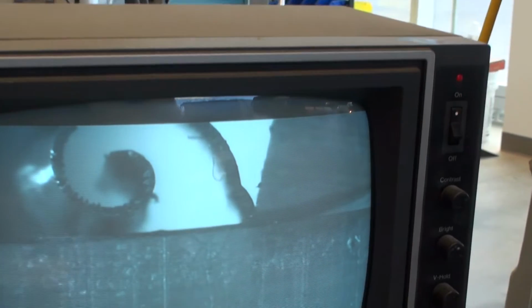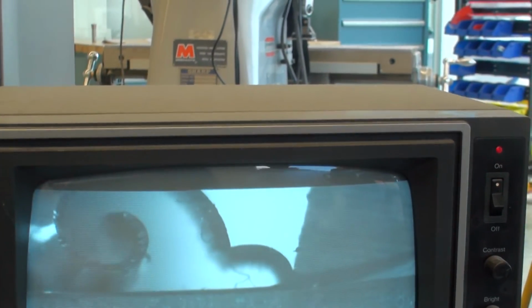So this time we see our chip forming, again making a curl, but its curl's a little bit of a different configuration, and it started to curl over earlier. And in fact, now we see that the chip itself broke and it's making a second chip now. So we've now made a discontinuous chip. We're still only about halfway across our piece of material.